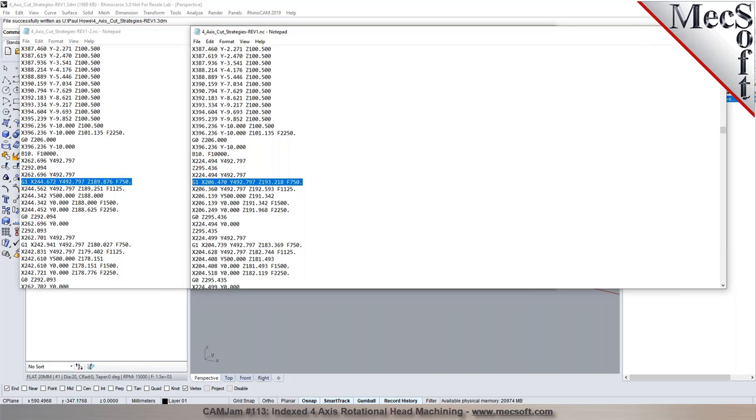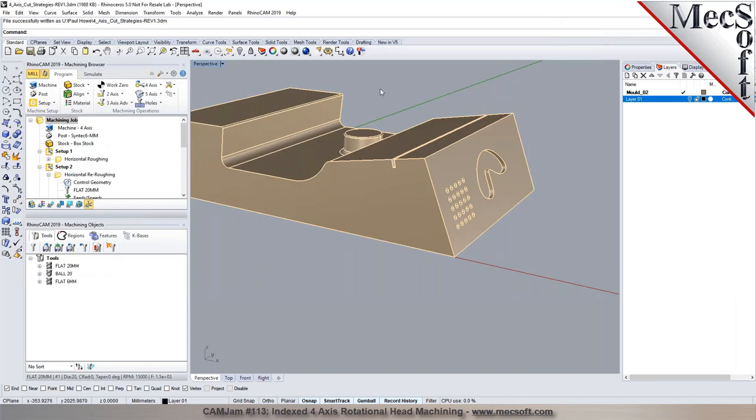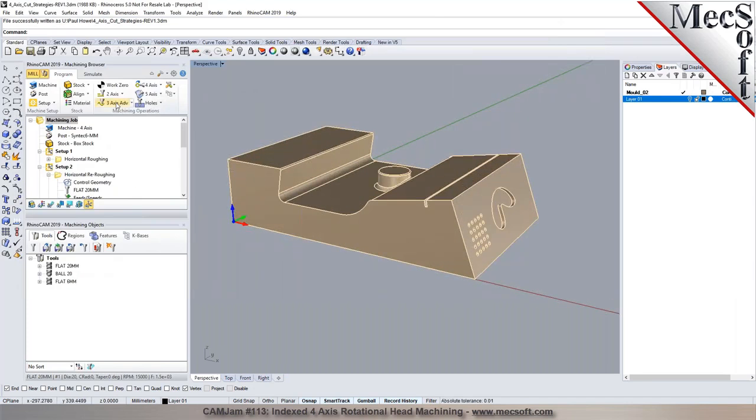If the gauge length is not specified, which means it's 0, then the tool length also doesn't get added to it. So that applies to machines where the control can handle the gauge length. Okay, and I'll need to figure that out once the machine's here and I'm a bit more familiar with it.